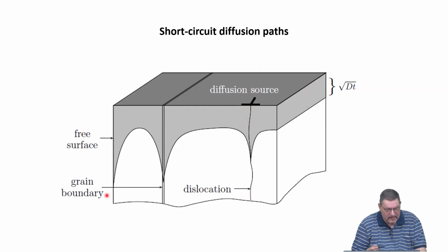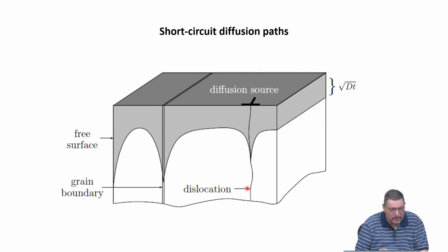It is easier to neglect volume and dislocation pipe diffusion because they are slower. So we could mentally think we just do an experiment for a sufficiently short time, so we will not see an effect of volume diffusion, we will not see dislocation pipe diffusion, but this one will be faster, so we will see grain boundary diffusion.